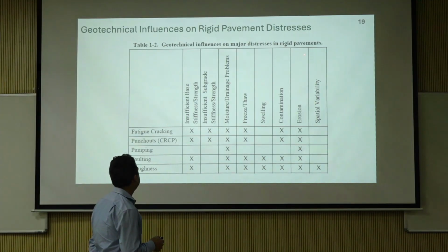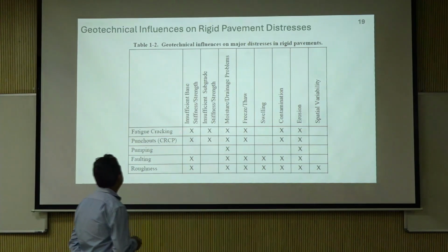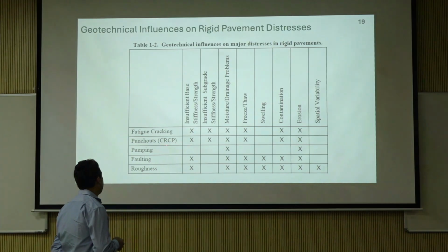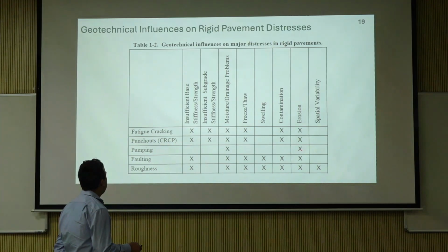Rigid pavements, okay, fatigue, punch outs, which is seen on continuously reinforced concrete pavements. Pumping is a big erosion issue.